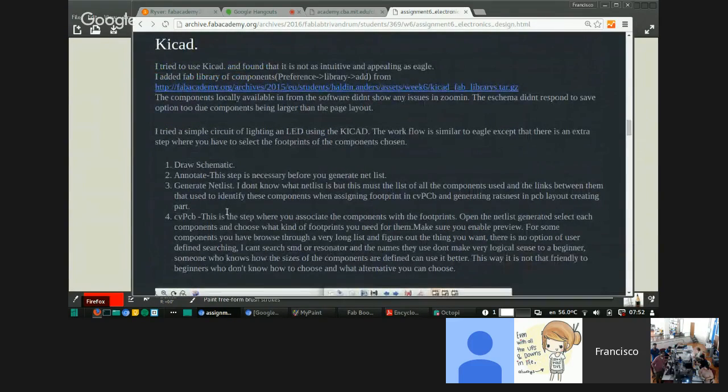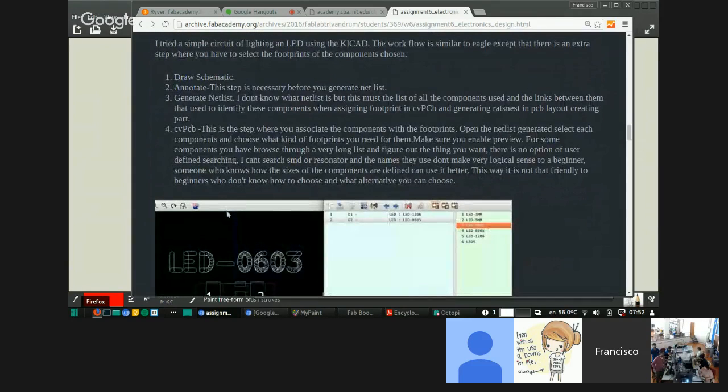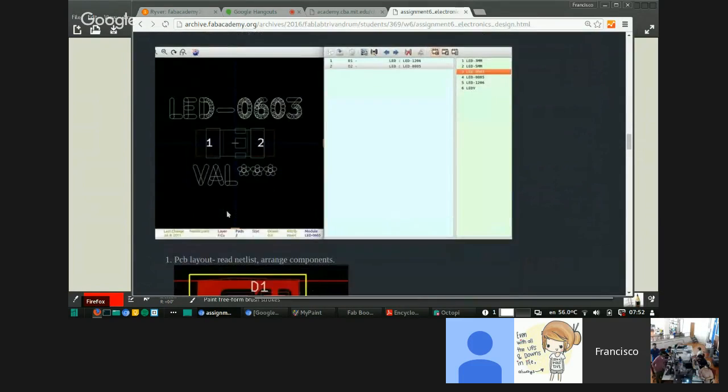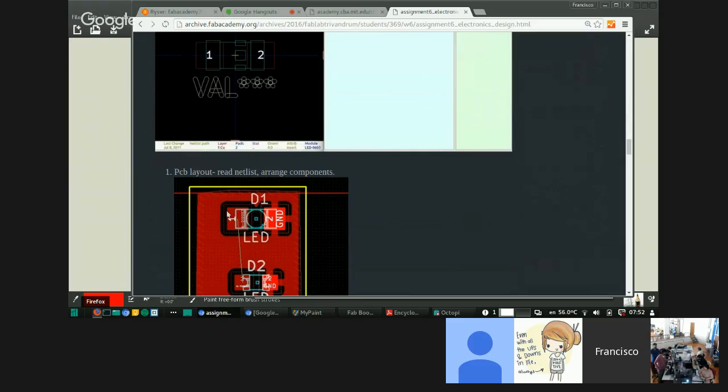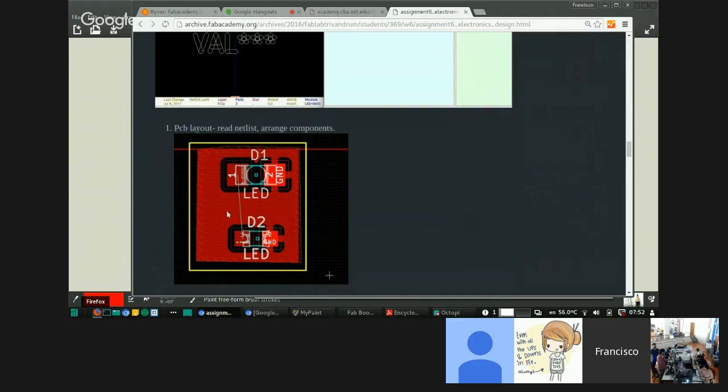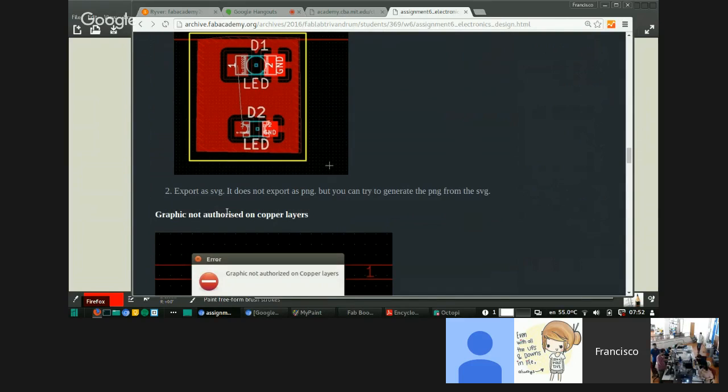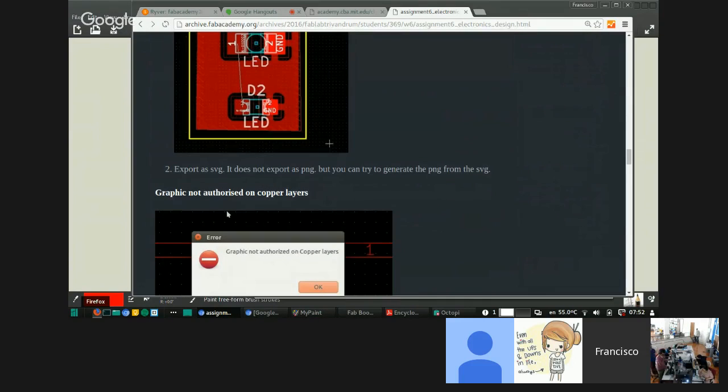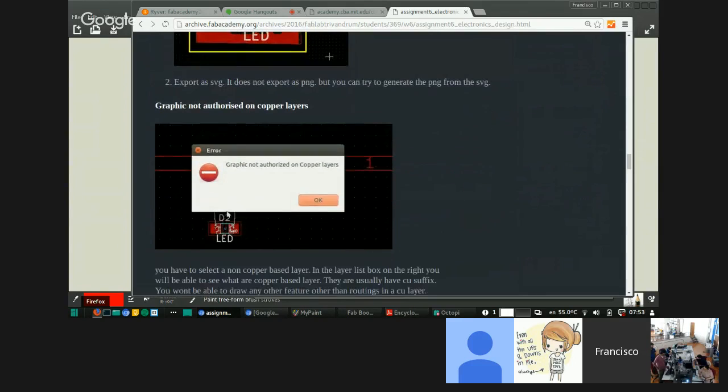Then use KiCad. How is KiCad compared to Eagle? It's not very intuitive. It does almost all the job as Eagle. It doesn't have auto routing options. You have to download another tool for that. It's kind of hard as compared to Eagle, but you can do pretty much anything which you can do in Eagle. The only part I faced difficulty was finding the footprints of the things which I required. You have to either create it on your own or somebody should provide.